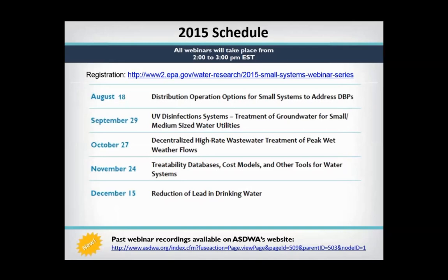And actually, even if you're not doing phosphate addition, if you get too much aluminum in the distribution system, you can still occasionally get aluminum hydroxide precipitation, which is also another pipe surface fouling mechanism, which can then give particulate release of lead. So those are the main concerns with it, I think. Okay, great. Thanks, Mike. A couple of people popped in and made comments that the state agencies can lead a person to a certified analytical lab. So that's something that our listeners have chimed in on.